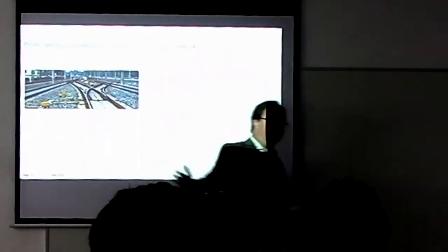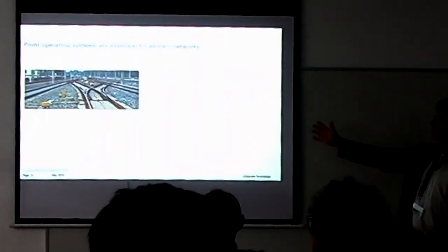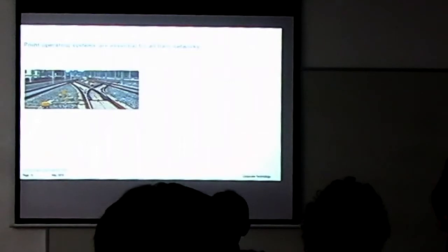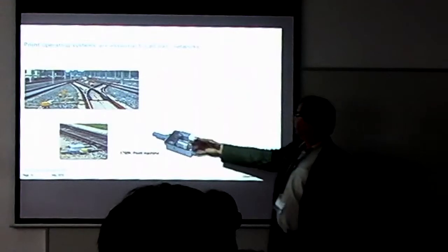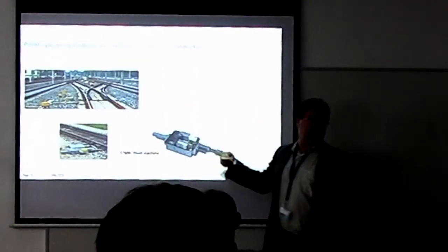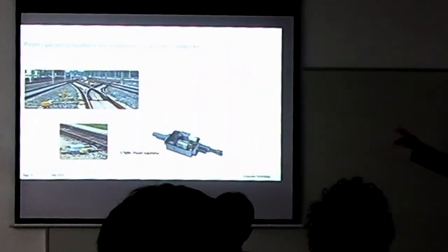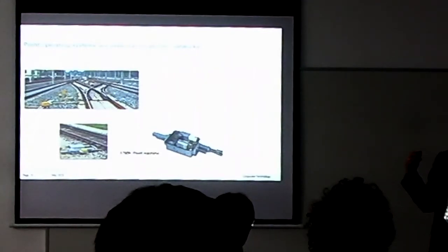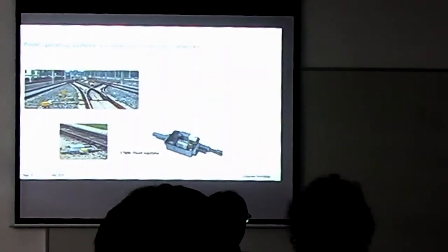Actually, the point operating machine is the drive that operates the train plates in the network from left to right. It's actually a very simple system. There's a motor in there, and you have some mechanical drive that turns the rotation into horizontal movement. This point machine, the S700K, has been sold for many years. As soon as I started working on it, I saw them everywhere in train networks all over the world.